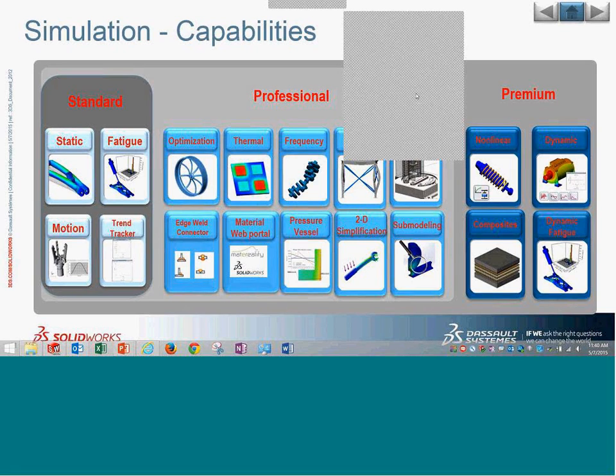And wall thickness is what you are looking at as a variable. We specify it. Now, obviously, there is no option to specify percentage, but you can specify the absolute values. That is, the wall thickness varies from 2 millimeters to 4 millimeters. So you can do it in that way.